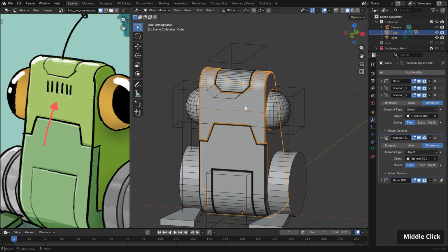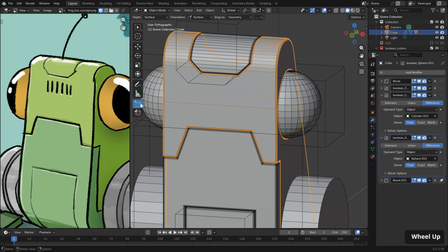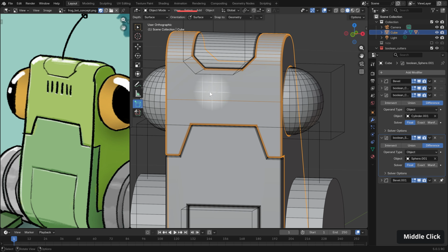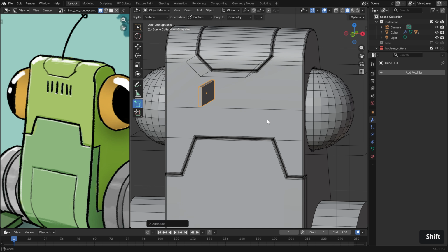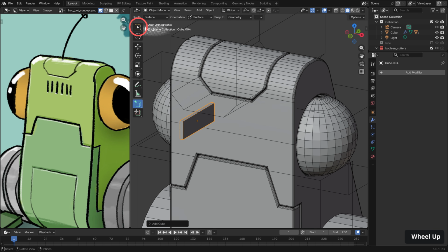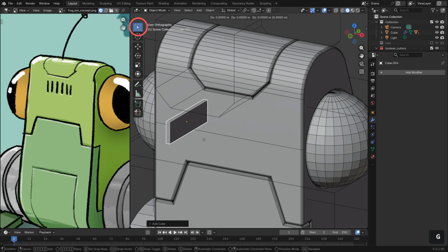And to do that, we can simply use a cube, and we can use our make primitive tool here. As it's set here, we can see it is snapping and oriented to surface, so we can just draw it straight on our surface. So going to select here, draw a profile like that, and extrude it out. There we go. Let's move it in so it's actually cutting something. So G and Y, moving it in like so. And we want 1, 2, 3, 4, 5, 6.